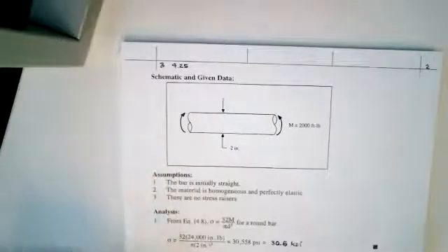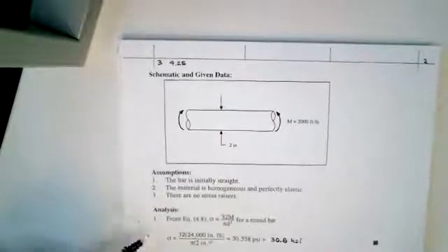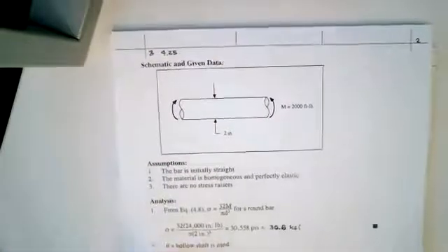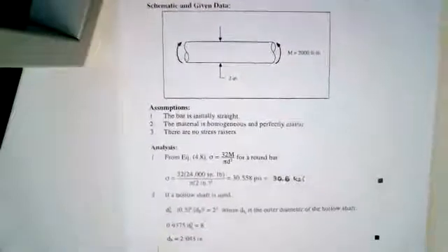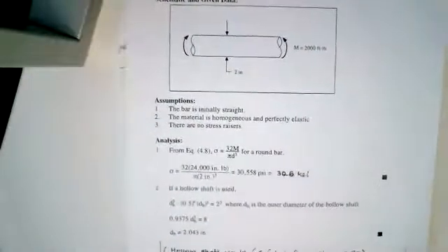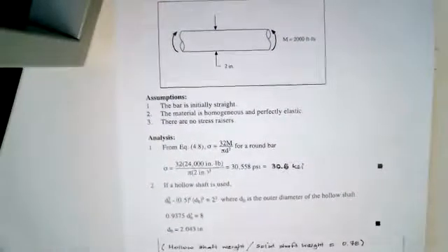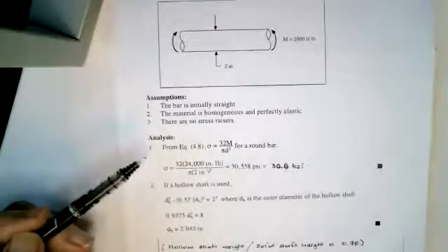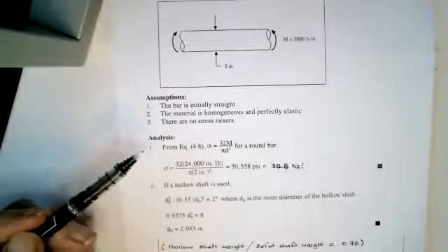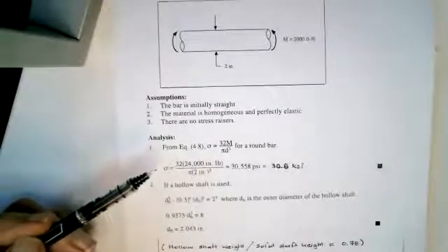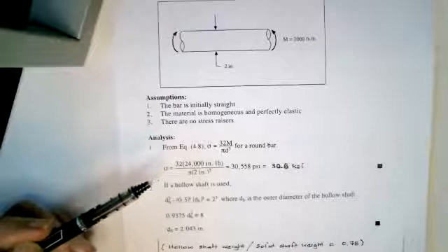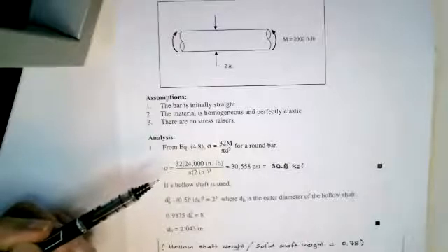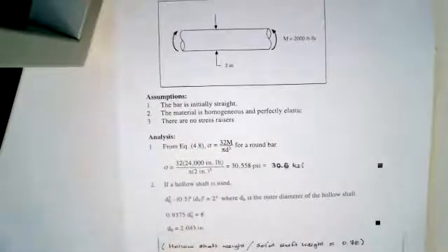And the analysis essentially parallels what I did for the torsional problem, and you get a reduction in weight. Now you have to be a little careful that if you make these two things too thin, you'll get buckling. Okay, and in the first example, the thickness was still about 1/4 of an inch. A 1/4 of an inch of steel is not going to buckle too easily. We'll talk about buckling later.